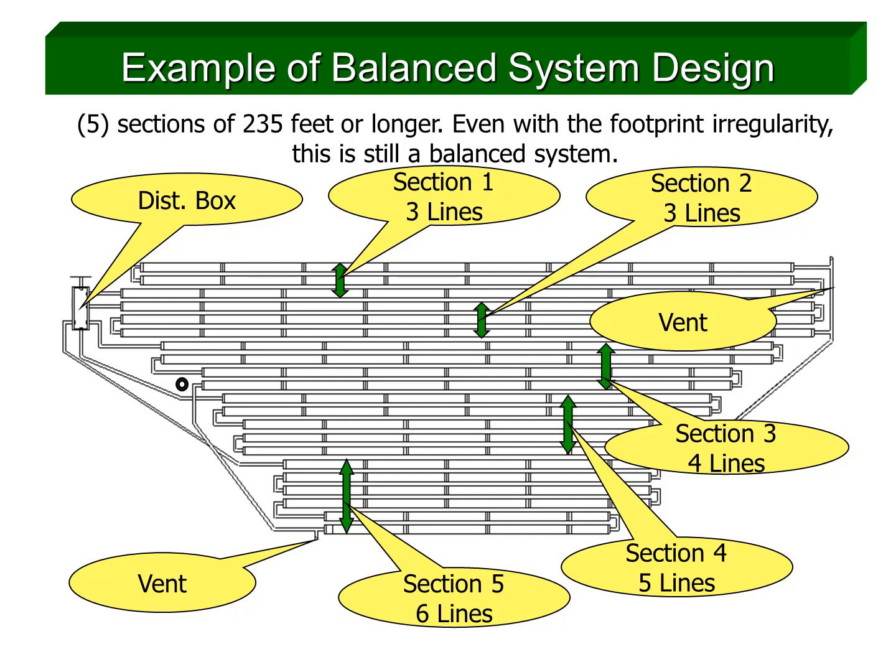For example, if a given daily flow required 1,175 feet of pipe, with 5 serial sections, then each serial section must have at least 235 feet of pipe. If due to site constraints we couldn't make our field rectangular with all the rows the same length, and instead had to use a triangular shape as we did for this McDonald's system in Alton, New Hampshire, row lengths will vary from section to section. This is acceptable as long as the total amount of pipe within each section is at least 235 feet. So to illustrate, one section could have 5 rows, with the first being 60 feet long, the second 55 feet, the third 50, the fourth 40, and the fifth 30 feet long. The total amount of pipe is 235 feet, which satisfies the rule.